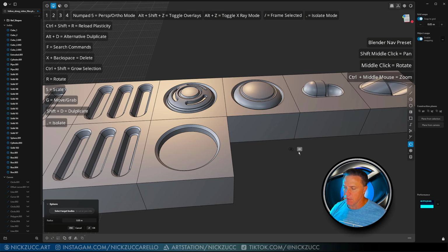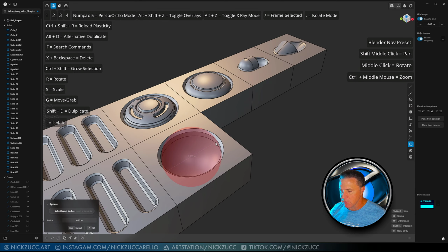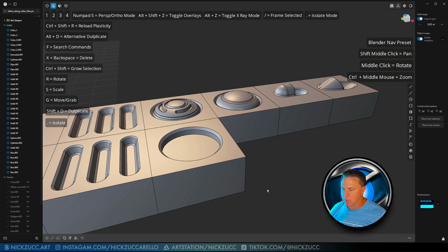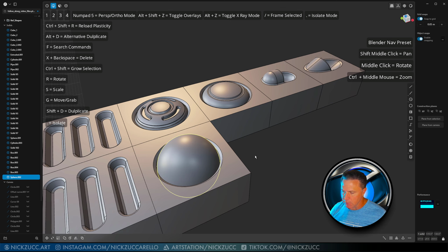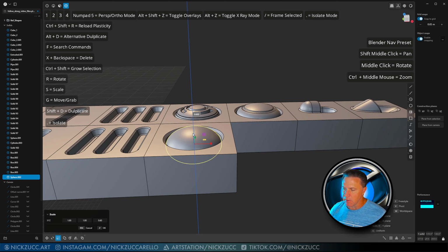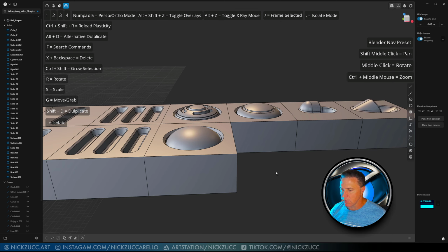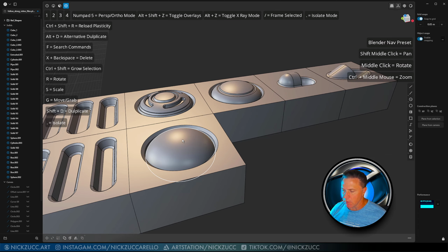I'm going to go ahead and do a sphere, and I'm going to click and then drag out from the center, and I'm going to click this edge here like this, but I'm going to tap B for a new body. Right click to confirm. Let's try that again. Not sure why that failed. I'm going to click out, tap B for new body, and then just click here, right click to confirm. Okay, so I'm going to tap 4, select the body, tap S, and I'll just scale that down just to squish that sphere like that. And so then that should give us something pretty similar to what we've got going on here.